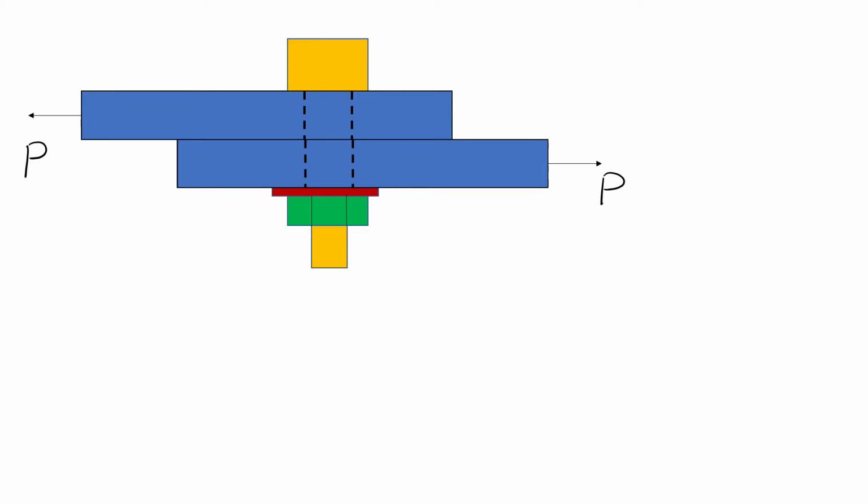In some types of structures, notably bridges, the load on connections can undergo many cycles of reversal. In such cases, fatigue of the fasteners can become critical if the connection is allowed to slip with each reversal, and a slip-critical connection is advisable. In most structures, however, slip is perfectly acceptable and a bearing-type connection is adequate. A307 bolts are used only in bearing-type connections.